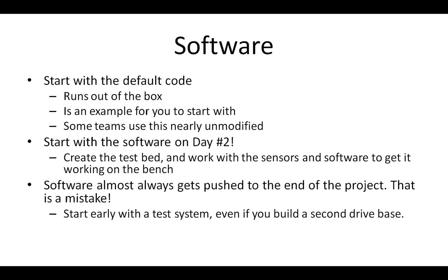Really do that immediately. And if you can, hey, if you've got the parts or if you've got the inclination, even building a very simple secondary robot base, you know, order another chassis or build something out of wood, slap a couple wheels on it and a couple of motor controllers in that cRIO, and you'll be able to build a second control system that you can test on. Okay, really, really a great idea.